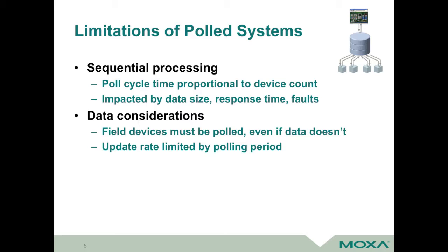How about some considerations on the data? What about if I've got some sites that I need to refresh the data a little quicker than others, right? I might have something where the process is a little quicker and I need to respond a little quicker, versus maybe I'm looking at a tank level, and that tank level may vary every 30 minutes, right? So that kind of goes into consideration on this.